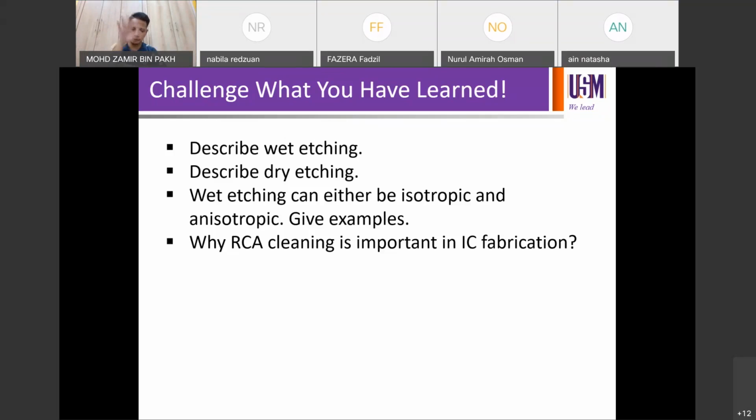So you have a planar silicon, you put it into an isotropic wet etchant. You leave it for a few minutes, for example, then you pick it up, and then what do you get on the surface? What sort of features do you get? Usually for HF plus HNO3. No, not pyramids. Pyramids will be in the anisotropic case. Right, either inverted or upright pyramids.